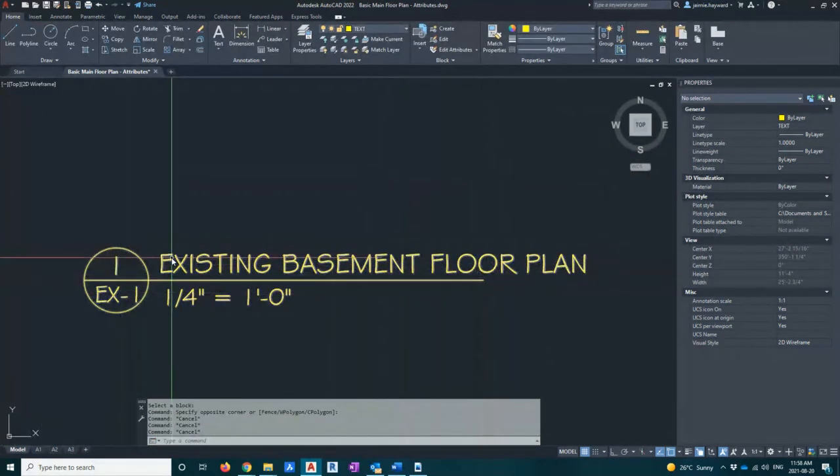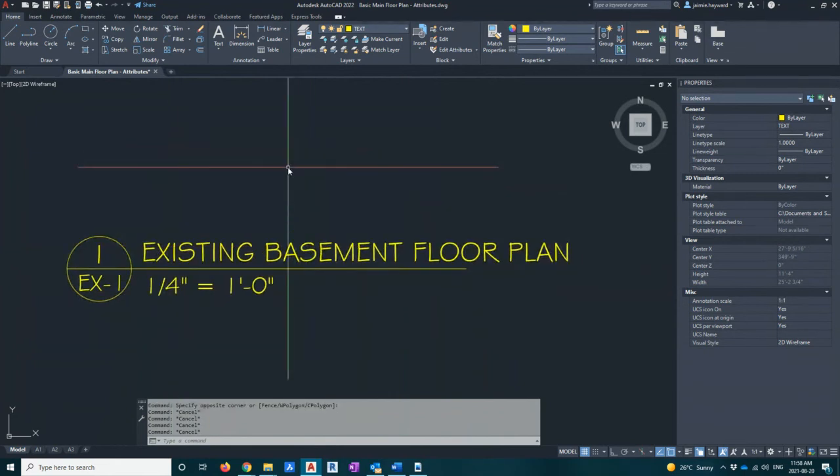Now what happens if I want to edit my objects? Like if you want to edit something in your title block, in that box, or this line, I want to edit something like that. Well, that is a completely different command. That is the command REFEDIT. This stands for reference edit. Reference edit means I'm editing the block itself, not the attributes, the block.